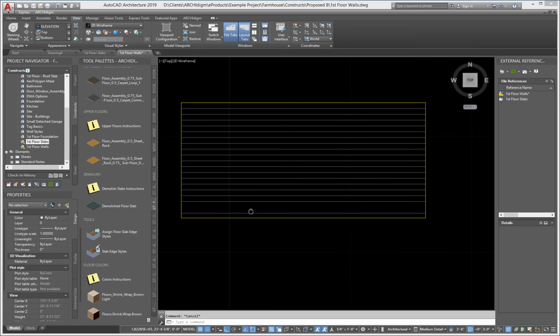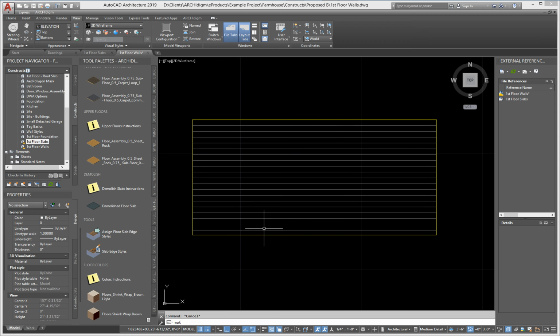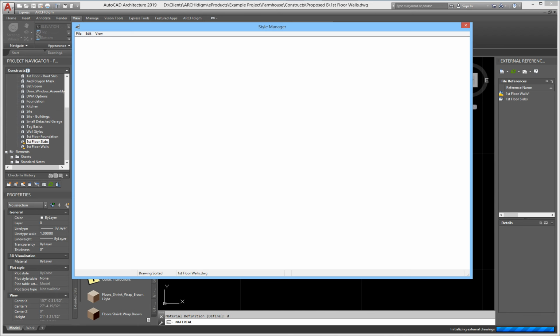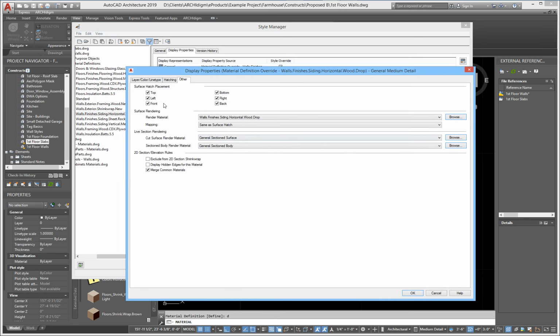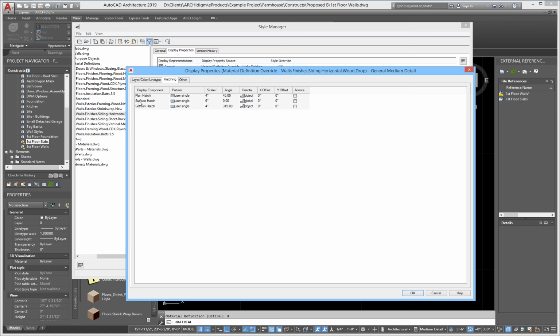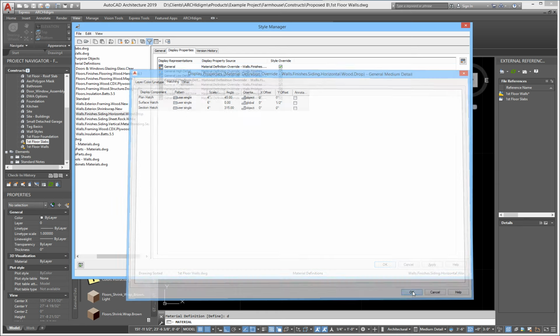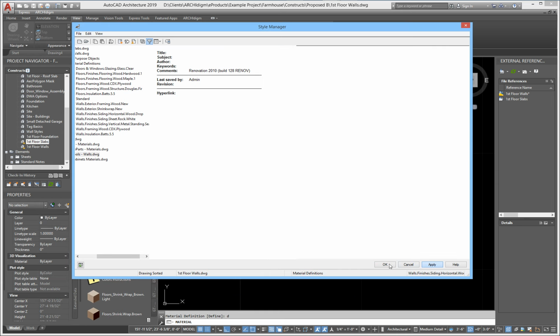There is another little thing you can do if you go back to material, D for define, and you go to drop siding, general medium, and you go to your hatch. You'll notice here what's being used is the surface hatch pattern. And it's set to global, and I'll talk about why global is the better choice. There's two choices, object or global. So what I found here is if you bump this up, I think you can get away with like 1/2 inch. It varies for the material and the conditions, but I think in this case all you need is 1/2 inch, maybe an inch.